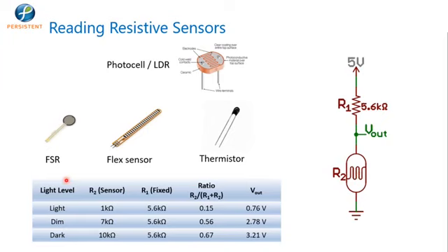So, in short, the light level, and the values of R1 and R2 as I am highlighting, R1 kept as constant, but the change in this resistor value here will vary the voltage output. Now, according to this change in the output, probably you can take an action, whatever actuation you want to carry out on the change in the light intensity.